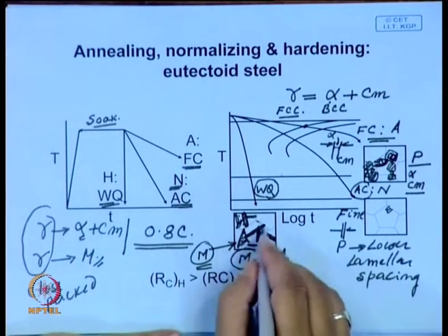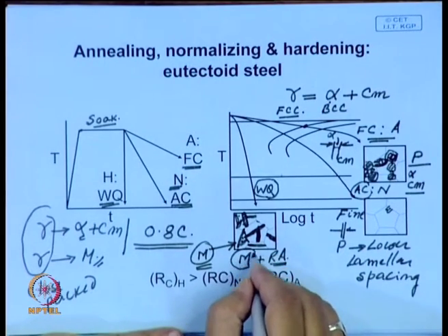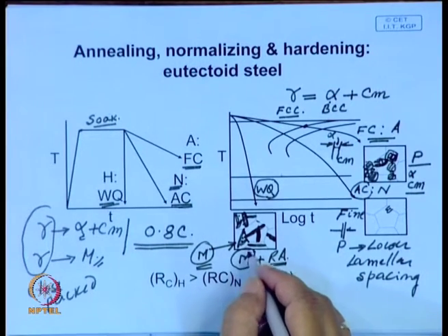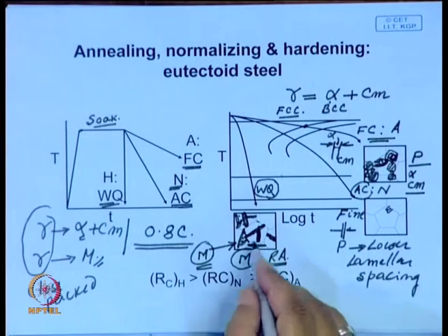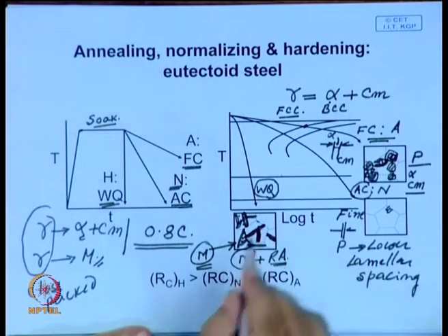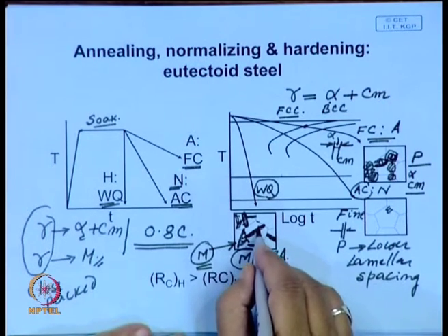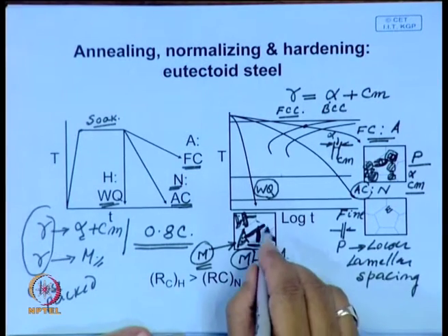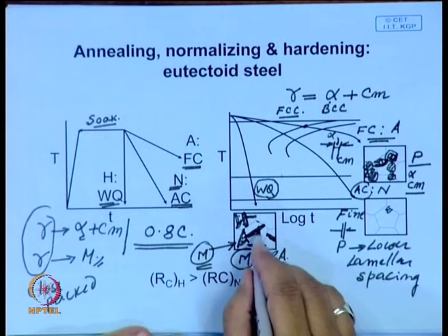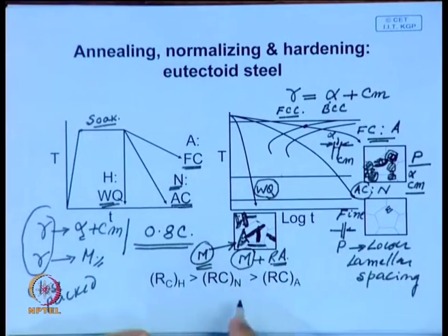The structure will be so fine that it may not be resolvable, and in fact, under an optical microscope these martensites are very bright, and they often do not etch well. But if you temper it slightly, as we will see, they etch very well and you can see this structure even under an optical microscope, but not the final details within one plate of martensite, because there the level of resolution needed is in the nanometer region, which is extremely small. So, you need an electron microscope to resolve the structure within the martensite plates.